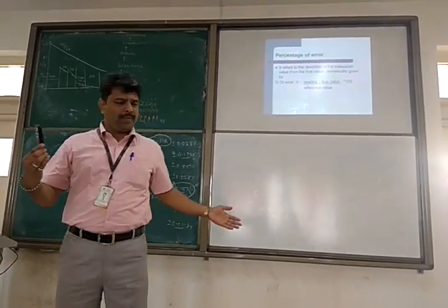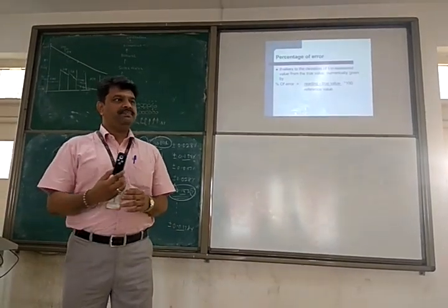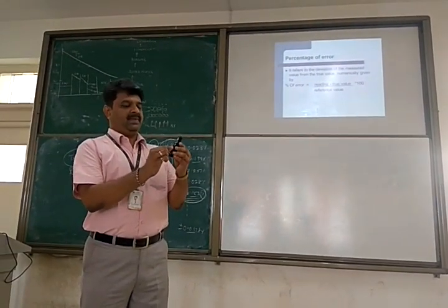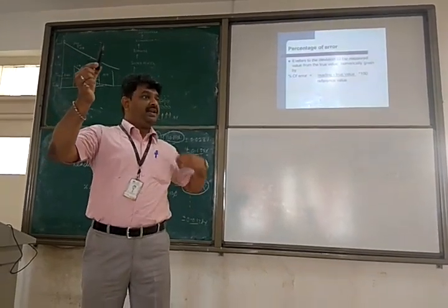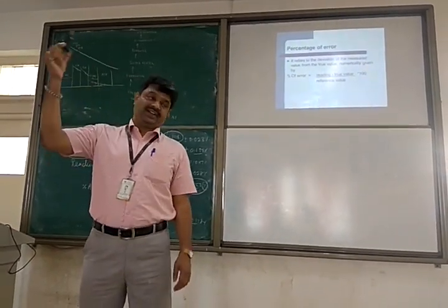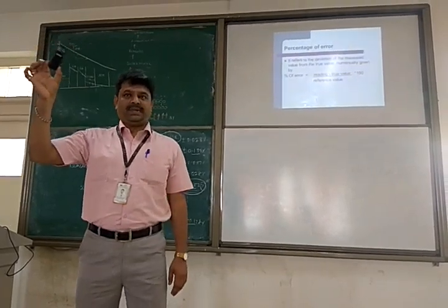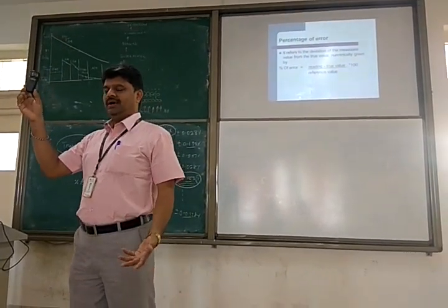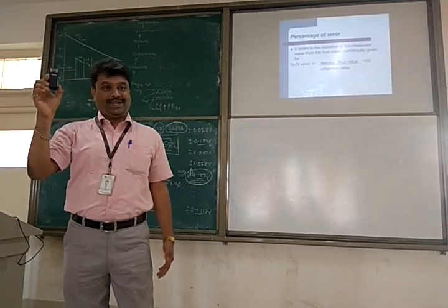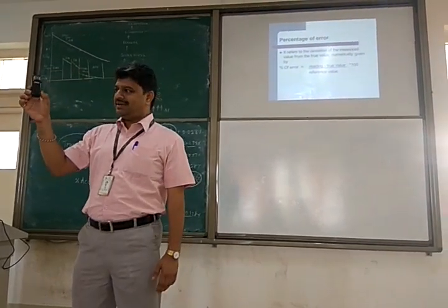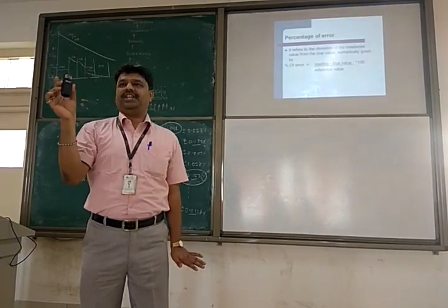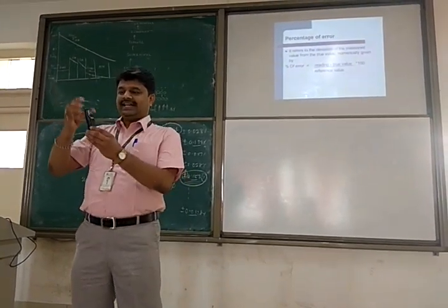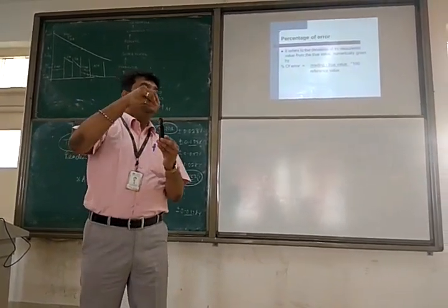I did so many experiments as I explained to him, and then assigned a number, plus or minus 1% accuracy, for this instrument. That will remain valid till it is further calibrated. The plus or minus 0.1 degree, plus or minus 1% accuracy is valid till next it is calibrated. Okay, it won't change. It is the characteristic of this particular instrument.